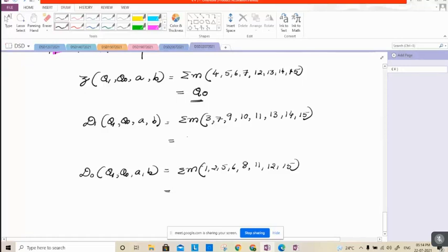So D1 equals AB plus Q1 of A plus B. So this will also be equal to AB plus Q1 into A XOR B. Please check it once, rearrange the terms, you will be getting that.